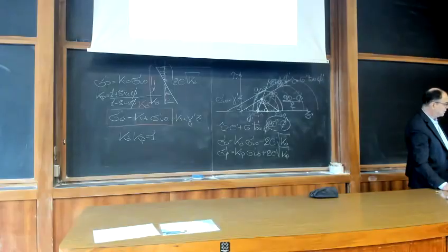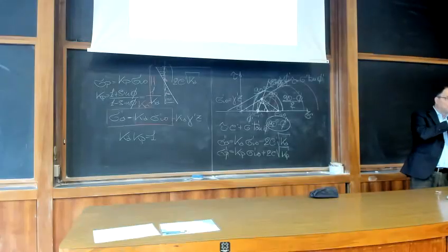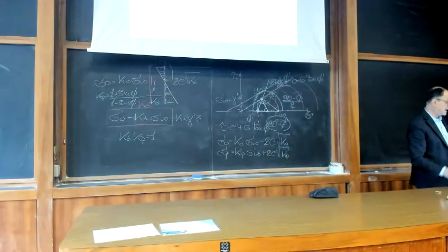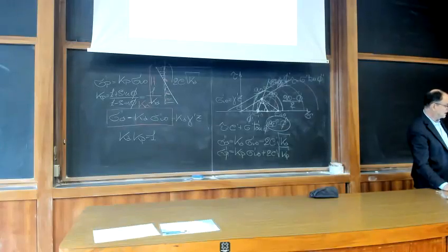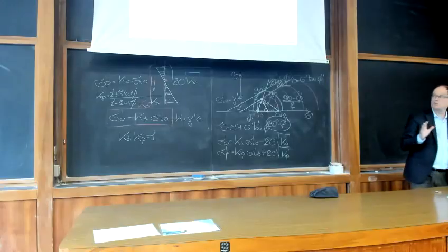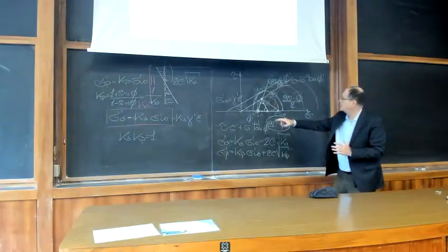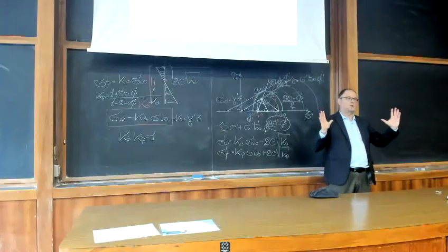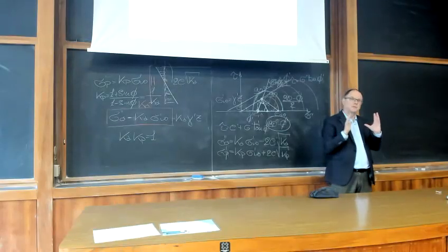For example, if you have this element, you see this is more typical like a simple shear of your soil. And if you look at the soil which is at the side of the footing, this is more typical like something passive, because you have no increase vertical, but you have increase horizontal.